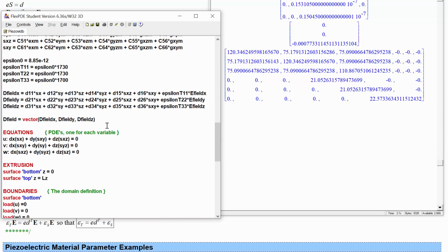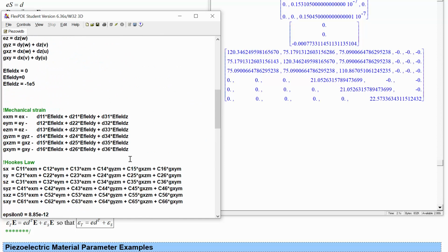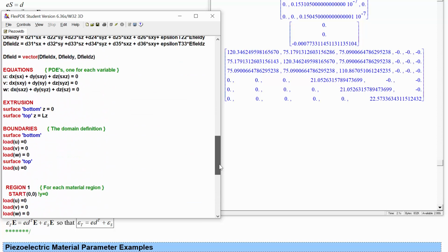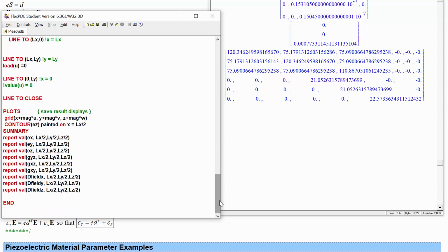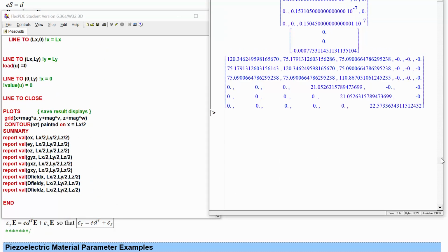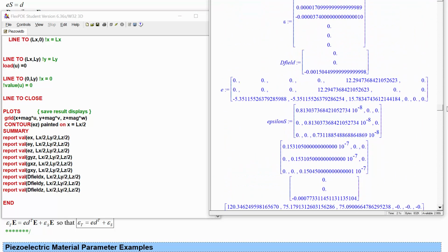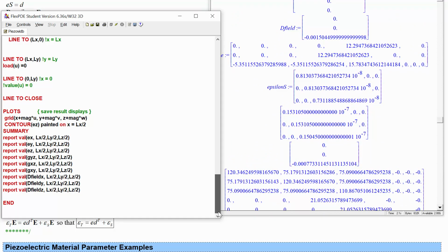And now let's see if we can apply some boundary conditions. If we are understanding everything correctly, we should be able to get an x-directed charge displacement, even if the electric field isn't leading to anything in x, if we were to apply the appropriate strain to this material. And that strain that will do it is an XZ strain.